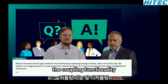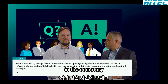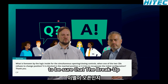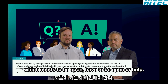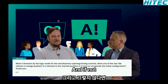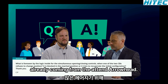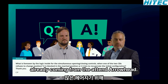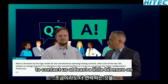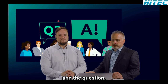I think we talk about the decoupling functionality, and the decoupling functionality is implemented, of course, in the simultaneous mode, because we send the open and the close command at the same time, and we have to be sure that the breaker which needs to be open is open. If not, then we have to trip the breaker which is already coming from the alternative source. Whoever has asked this question, do not hesitate to contact us, especially Sebastian, to discuss in more detail the application and the question.